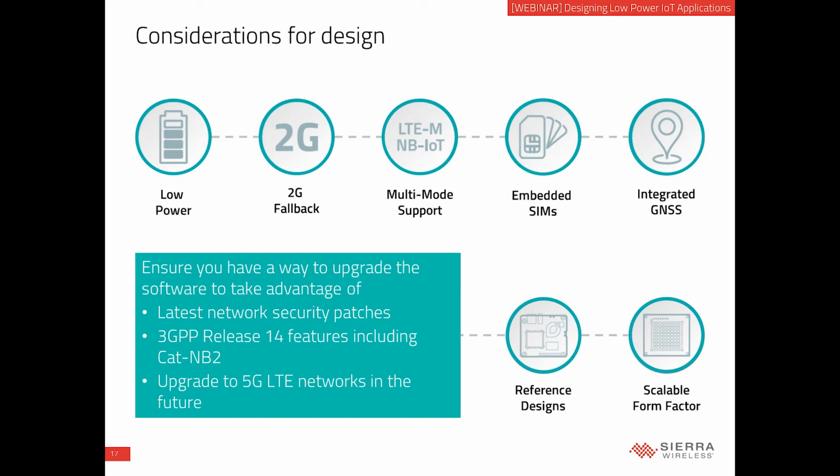But after a time, after 3-4 years, if you're not happy for whatever reason, if you want to change, using embedded SIMs, you can remotely reprogram your SIM. You don't have to go on site and switch the physical SIM. You can just reprogram it over the air and switch to, say, Orange, and then all of a sudden you're an Orange customer. And so this freedom is very important to keep in mind when you design your low-power IoT applications.